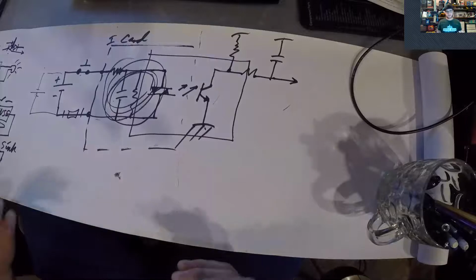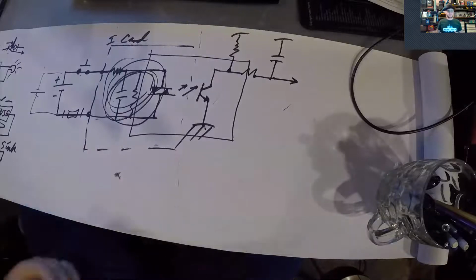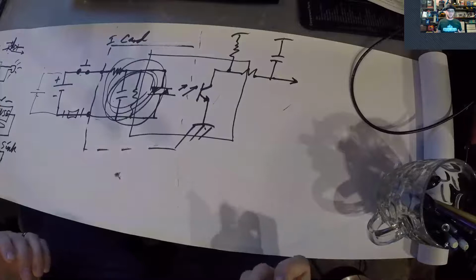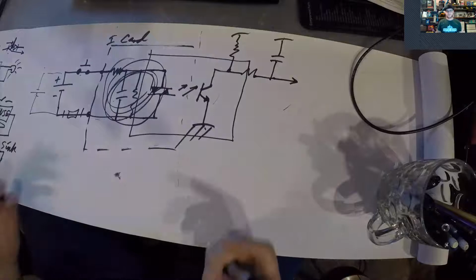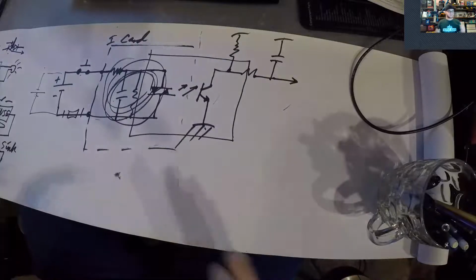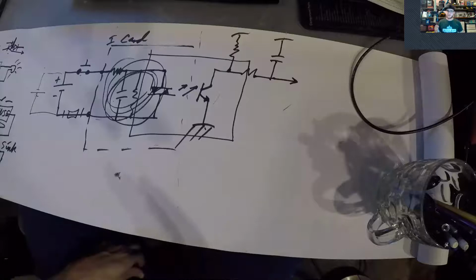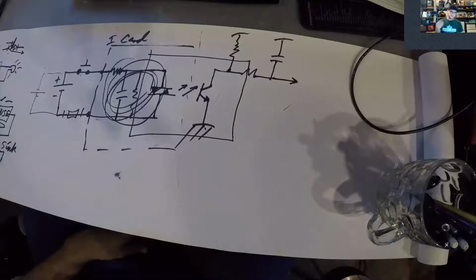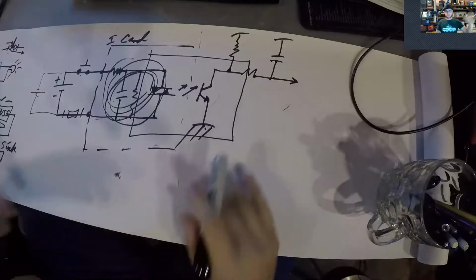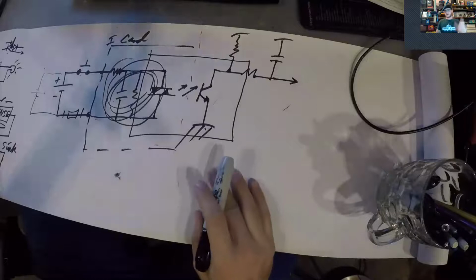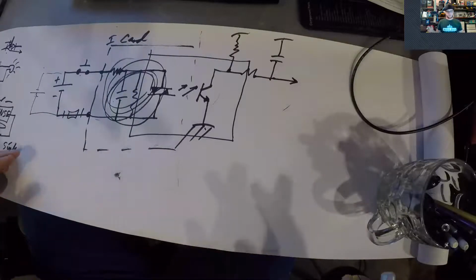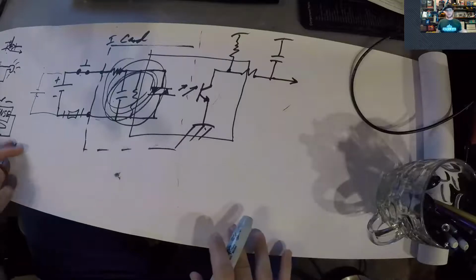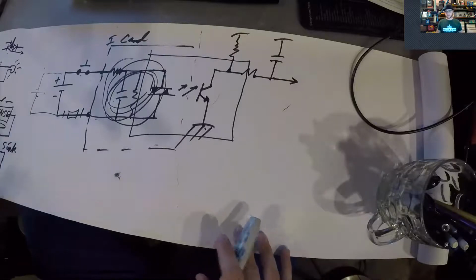I once bought a printer from a company that was getting installed on a production line, and I also bought a sensor from them to go with the printer. I told the sales guy this sensor is going onto this printer, it's going to be the trigger for this printer, and I didn't do my due diligence speccing out parts. I just told him, hey, this is the sensor I need, this model sensor for this printer, and he sent me a PNP sensor, and the printer was configured NPN.